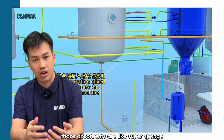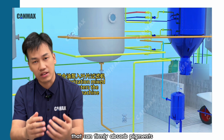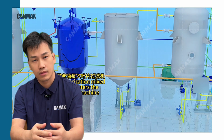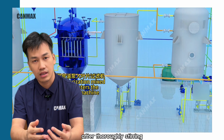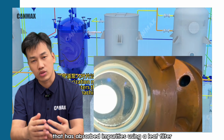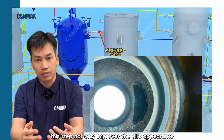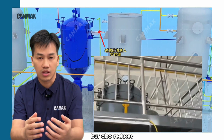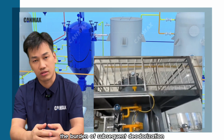Those absorbents are like super sponges that can firmly absorb pigments and some impurities in oil. After thoroughly stirring, we filter out the clay that has absorbed impurities using a leaf filter. This step not only improves the oil's appearance but also reduces the burden of subsequent deodorization.